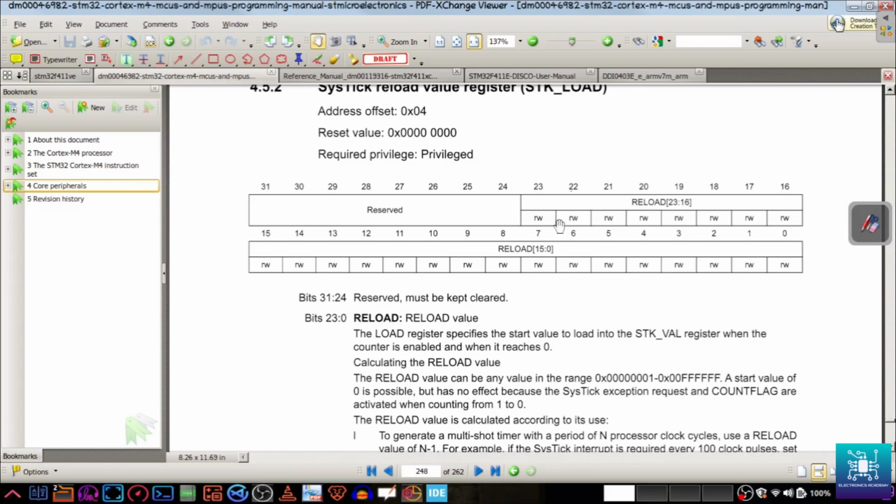So we'll do it here. In this case, let us assume that those 8 bits are these 1 2 3 4 5 6 7 8. So say from bit number 16 we have to do that here. Whatever we have here, from here we have to set these bits to 0 1 0 1 0 1 0 1. And if the default value is 0, then we could just OR it with that number left shifted by 16 bits.